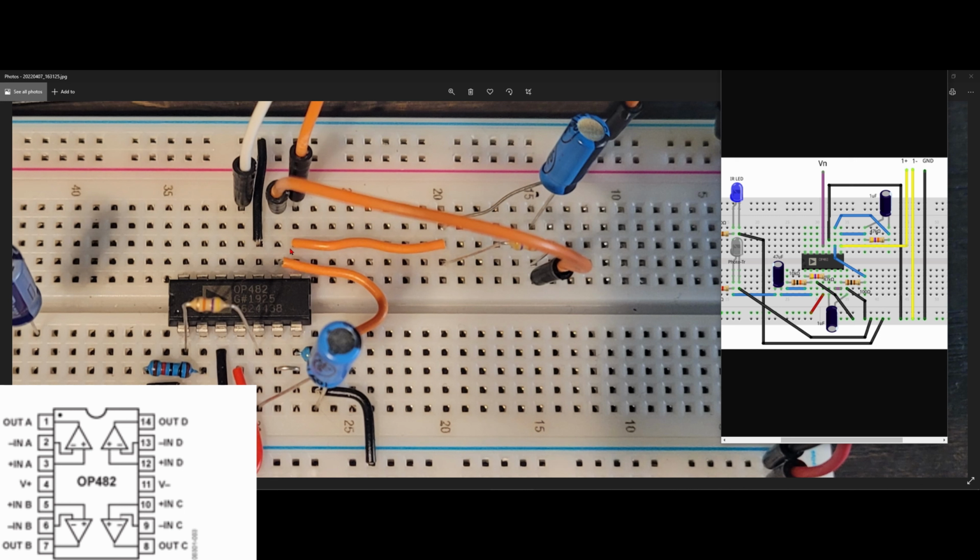Now the next wire is this one, this orange one right here, that goes from our output. This last column is the output. So the output into the middle of these two right here. And that's going to be about it. This one's grounded. We have our V1 and V minus. This is our waveform generator, right? So we want to monitor outputs. We are going to ground the V minus. That's the white wire, or the yellow wire with the negative strip. And then the solid yellow wire is going to go into this column right here, where I have the orange one. So that's going to go right there.